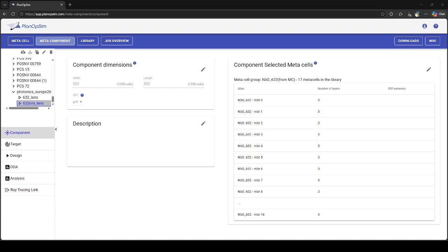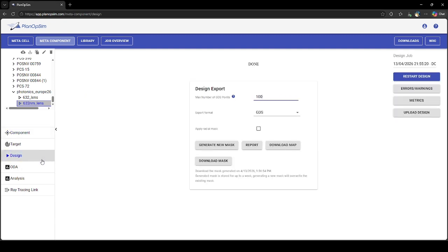Indeed, if we zoom in, we see our pillar structure, our different sizes that we've defined in a shape that closely resembles our face target, which is not surprising, of course, because the pillar mapping here is a representation of the face. You can see here in the center, we have different pillars going from the center through our meta surface. But this file looks fine, and we can go on to further analyze the performance of the meta surface.